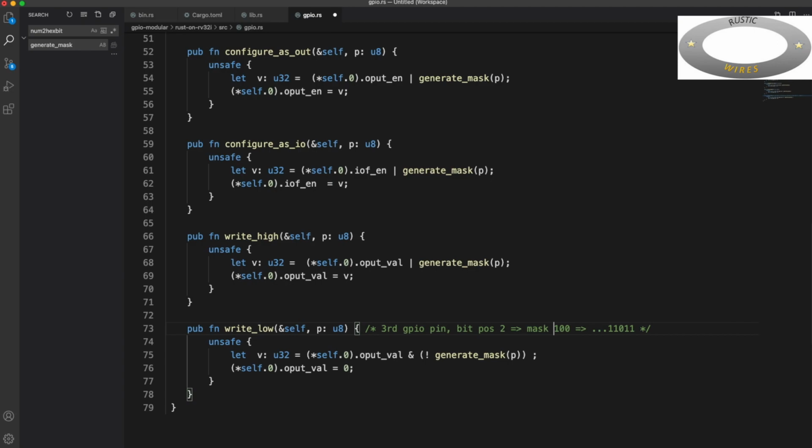Here you have the rest. So these are all the last 3 bits, and the last 3 bits in the inverted mask, the NOT of that would be this, and once you AND with this value, so this bit would be set to 0. Okay, so this is the right way of setting a particular bit to 0.